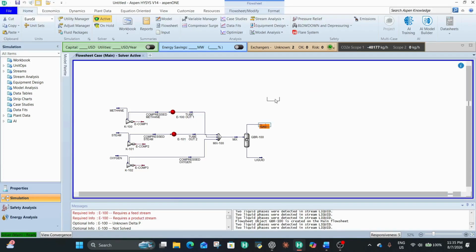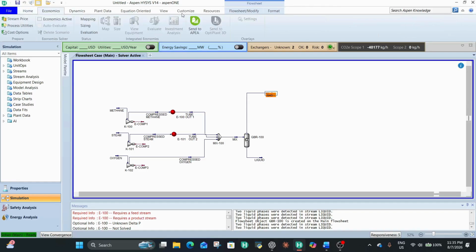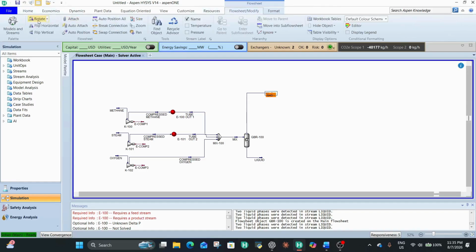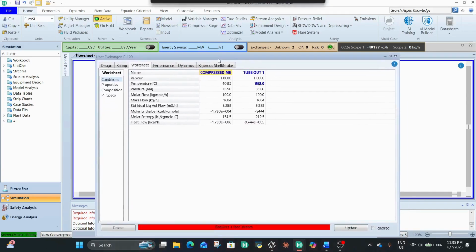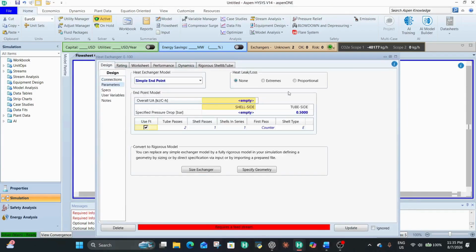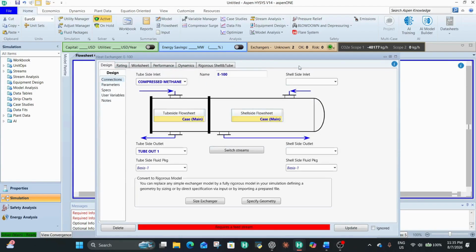Now, the magic we've been waiting for. Heat recycling, not to waste heat. We're going to inject this hot stream back into these two heat exchangers. Let's see if it's something that would work out successfully without temperature crossing. Remember the temperature crossing phenomena? If you're not aware of what that is, you should check that out.